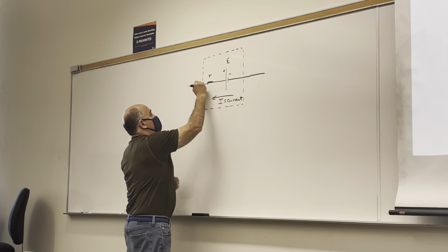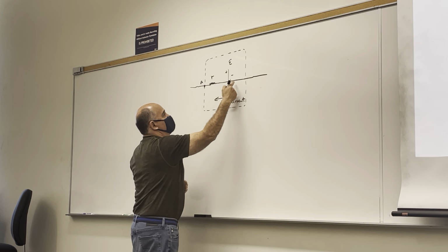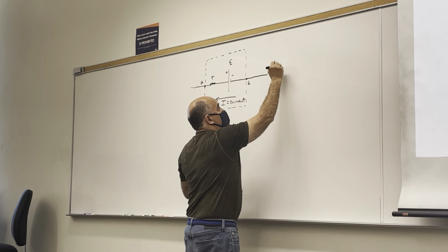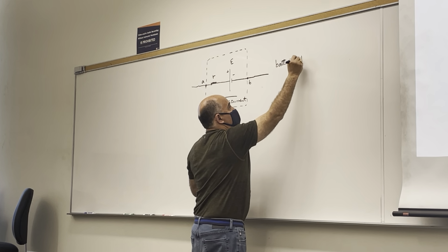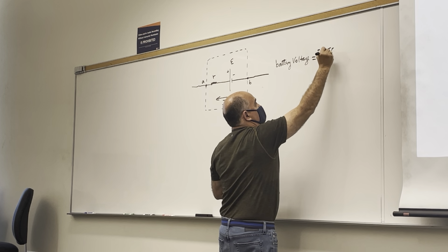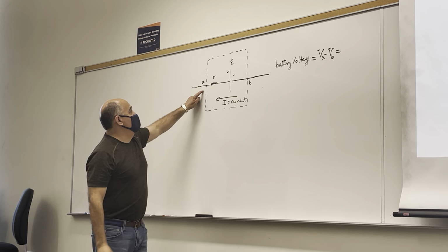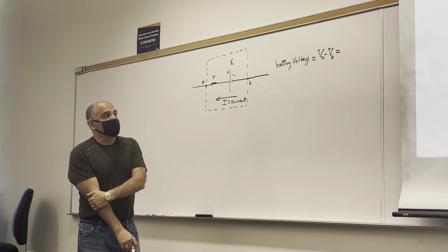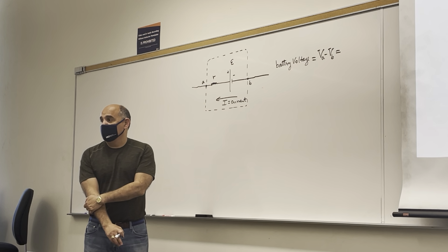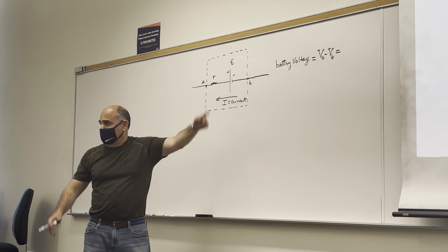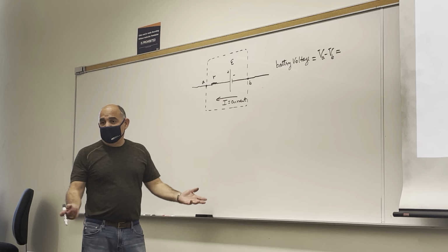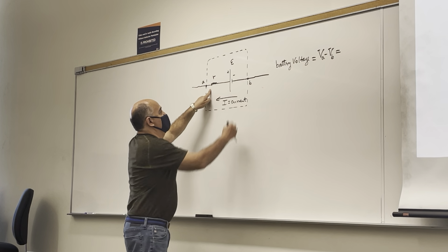Right. So I'm going to call this point A, because that's the positive terminal, and I'm going to call this point B. So the battery voltage is the potential at A minus the potential at B. Right? It's the higher potential minus the lower potential. So where do I start and where do I stop? I start at B and go towards A. The rest of the circuit, I could take that path, but this is general, so I don't know what's over here yet. That'll depend on the problem. But I can go from B to A along this path.